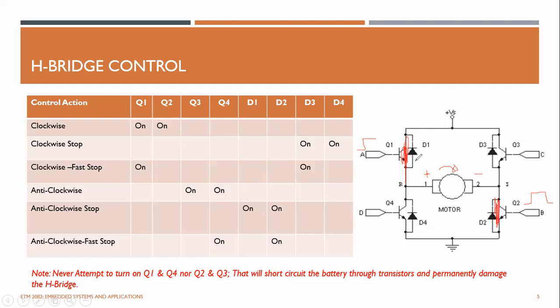And this is also short circuited to the ground. Okay. The diode direction is opposite, so there's no current flowing through the diode, right? So the diode is reverse biased. Now the current can come from this VS. This is something like a battery.